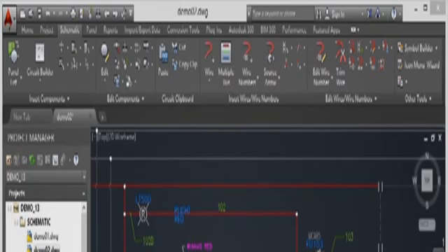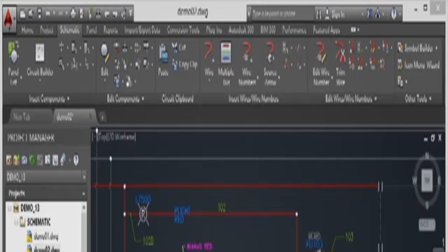So I click on delete component. I'm going to delete LT105A. I click on it, press enter to confirm. It goes and it says the parent device was deleted. Do you want to search for and surf to its child peer device contacts, if any? Which there are some. There's LT105 there. There's LT105B there. Now I'm going to say no in this particular instance. That just deletes it from the database, but 105B remains and 105 remains over here as well. That's how quick and easy it is to delete a component.